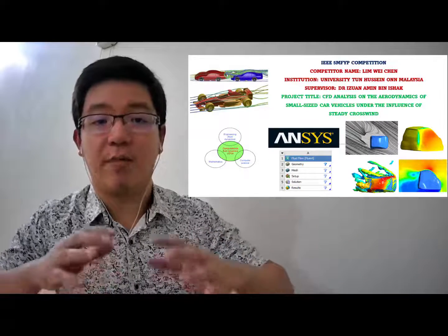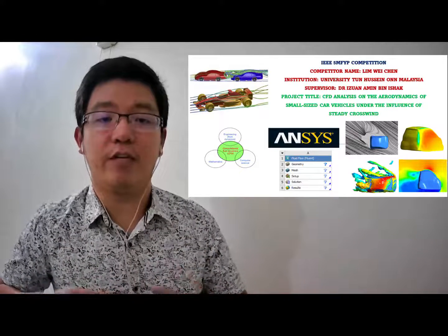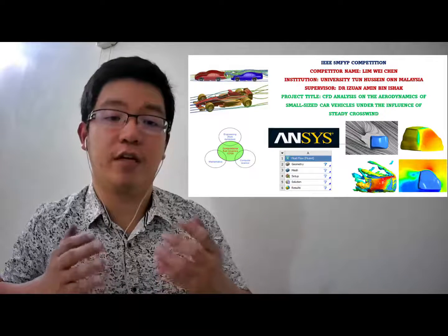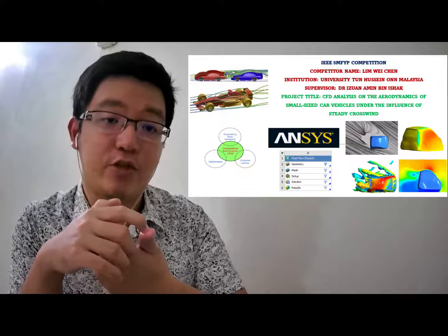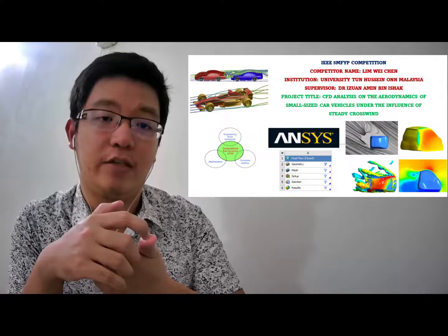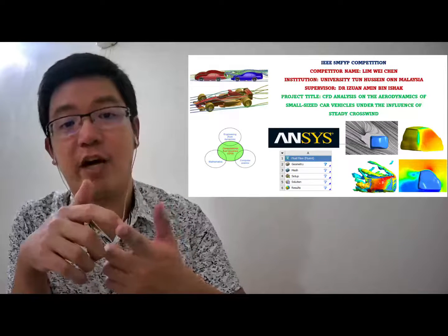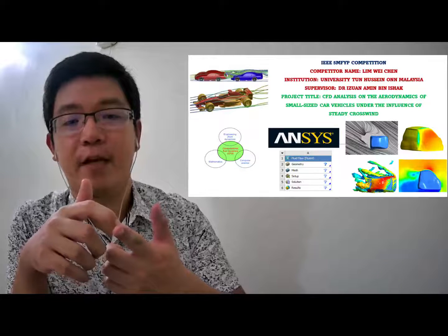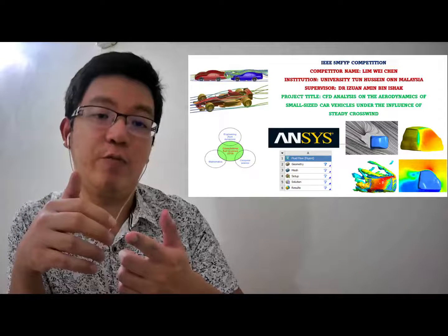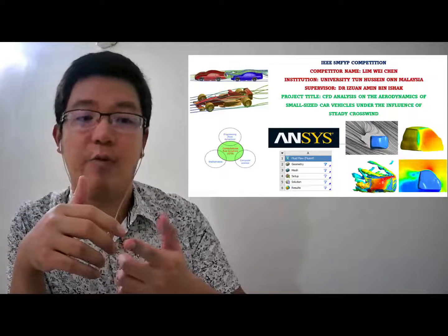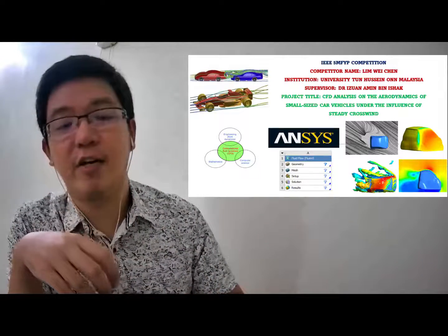Besides, it will help us get a picture of the flow behavior of the vehicle with respect to different crosswind yaw angles. For example, we will analyze the velocity streamline behavior with different crosswind yaw angles. We will check the leeward and the windward. The leeward is the side far away, which is known as the crosswind outlet, and the windward is the crosswind inlet. We will also check the behavior of the pressure projected on the vehicle.